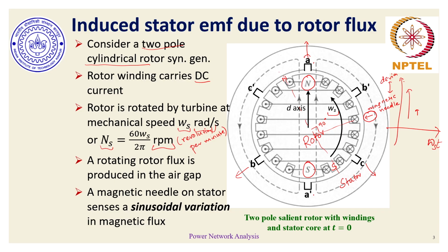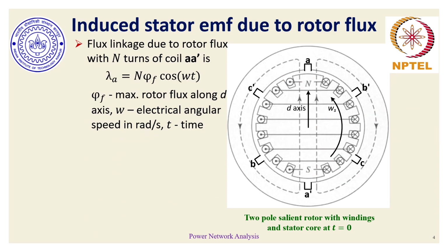So basically, the stator windings, which are similar to these magnetic needles, would also experience a sinusoidal variation in the magnetic flux, which is being created because of the rotor carrying DC current and rotating at the synchronous speed. And if we have to write a mathematical function for the system under consideration, the north and south poles are correspondingly placed at time t equal to 0.